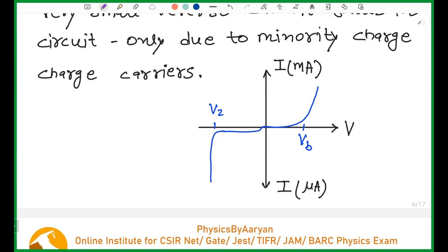At the moment, I also thought so, but the drift velocity of semiconductors is nearly independent of voltage up to a certain point. The attraction is more, but in order to achieve that, your collisions with the atoms will also start to increase. If you carefully calculate the drift velocity for semiconductors, you will realize that it comes out to be very nearly independent of potential up to a certain potential.